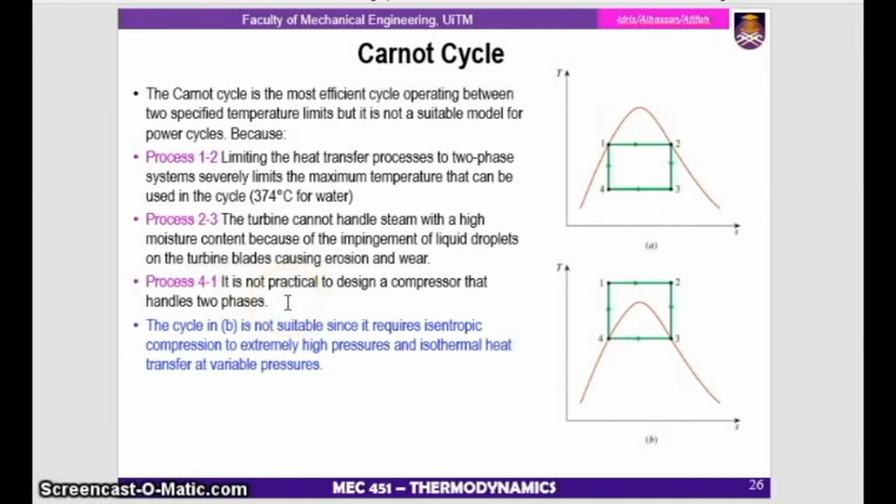Next, it is not practical to design the compressor or the pump that handles two phases. If you look at process 4-1, number 4 and 1 is a compressor or pump. That means it operates in the mixture region, so it is not practical to design.